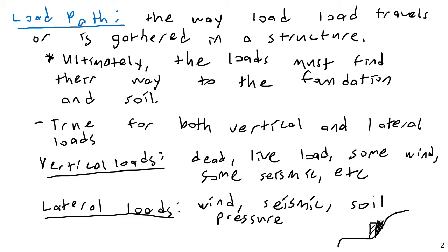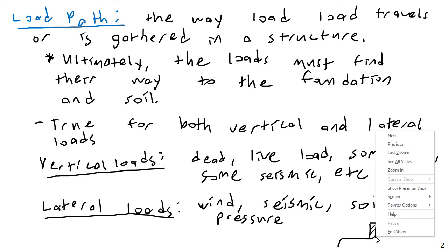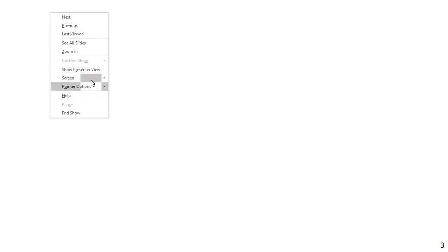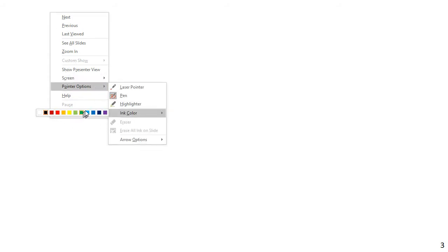Also, if you had a hydroelectric dam, or just a dam in general, the lateral load from water, the hydrostatic load, could be another lateral load. Okay, all of these are lateral loads. Now, next I'd like to look at how we consider load path for each of these. This is going to be a general discussion. Load paths can be quite complex, but I just want to discuss the theory very briefly and give some examples.